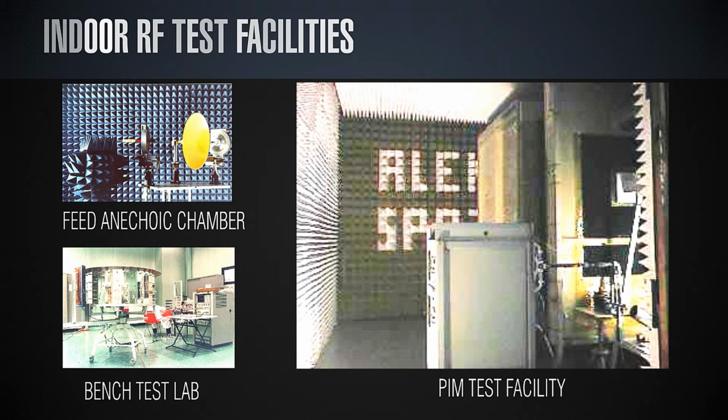test these antennas indoor. Then you have a chamber that is called anechoic chamber, in the sense that you have tried to avoid the reflections from the walls of the chamber. So the chamber simulates open space, and inside this you can put your test range and derive your radiation pattern. Indoor facilities are also used for all the components related to the antennas, to make many tests that are related to the realization of the overall antenna assembly.